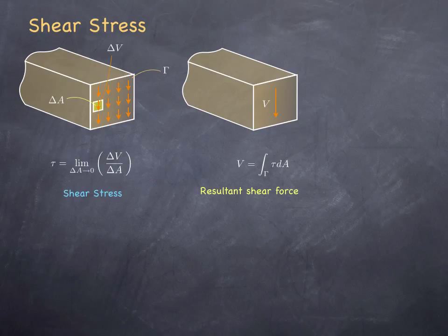But it is not always possible to go from a shear stress resultant to a particular distribution of shear stresses. And sometimes we take the shortcut and simply define the stress as some sort of an average stress by dividing the shear resultant force by the area over which it acts. Here's a small example of that.